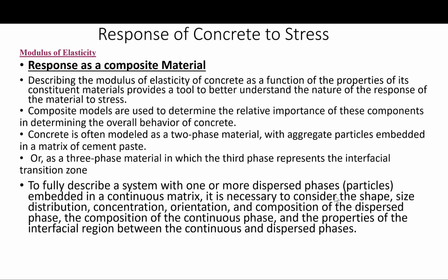Okay, so in order to study the response as a composite material, describing the modulus of elasticity of concrete as a function of the properties of its constituent materials provides a tool to better understand the nature of the response of the material to stress. The composite models are often used to determine the relative importance of these components in determining the overall behavior of the concrete. All right?